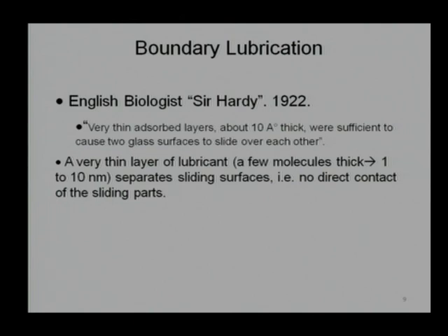Naturally, we are talking about the surface roughness, but above that we coat the boundary lubricant layer in such a way that surface roughness is not directly coming into the picture. Wherever the asperity touches, it will not touch the other metal surface directly, it will be touching a superficial layer, that will be the boundary additive layer.